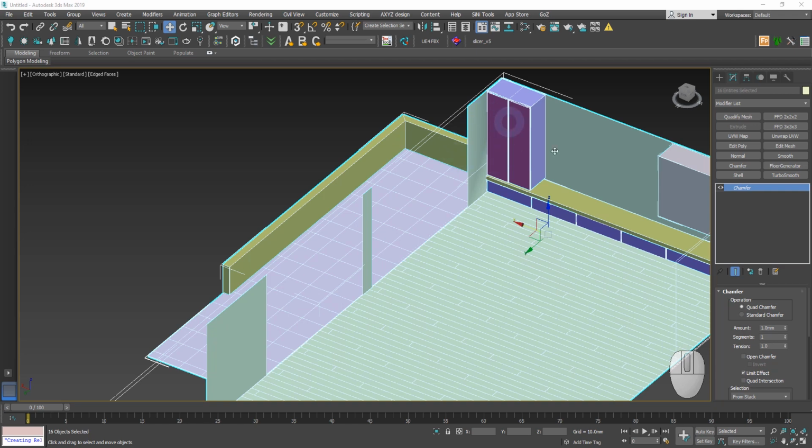We have to wait for chamfer to be applied to all objects. Set the amount of 2 mm in its settings. Set to segments. Every action may be accompanied by a slight delay. If that happens, you can try to apply chamfer to each object separately. Also check the Smooth Chamfers Only box in the end. Don't forget to save your project.